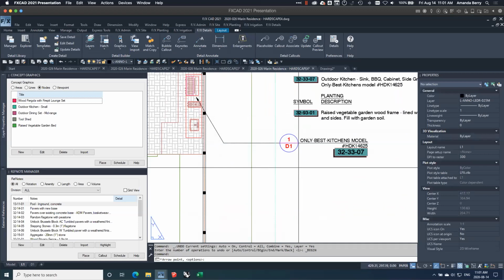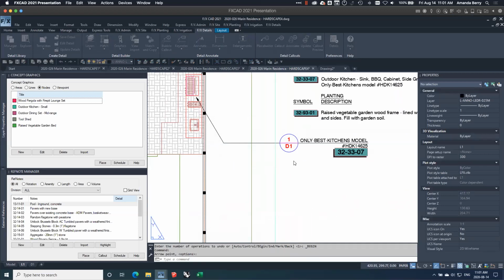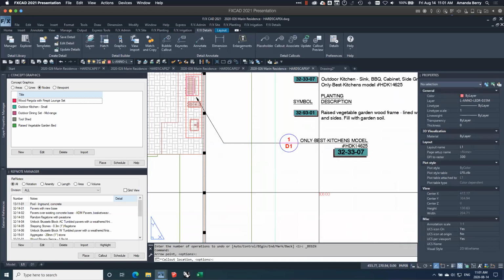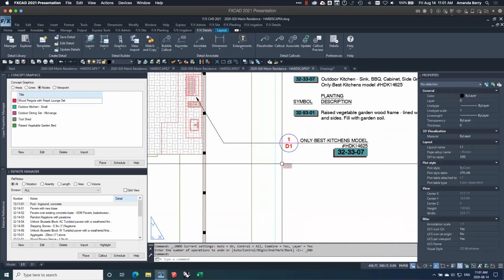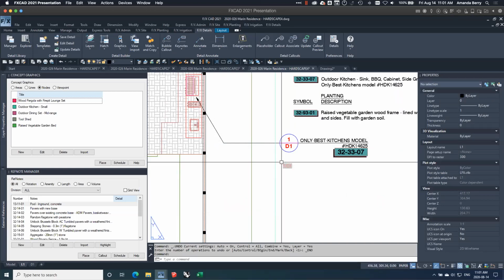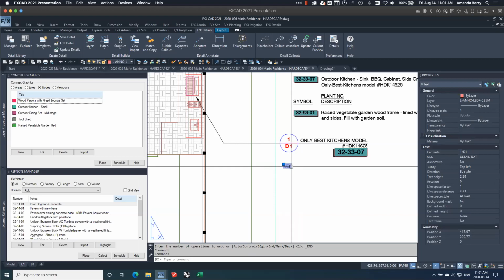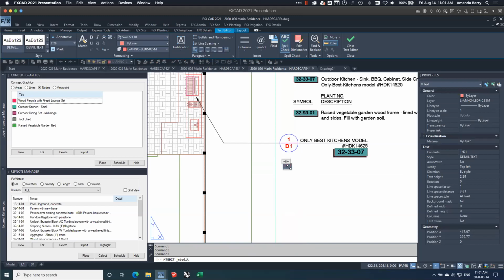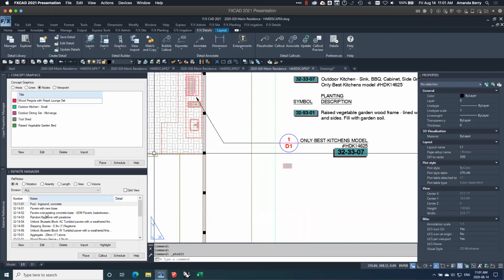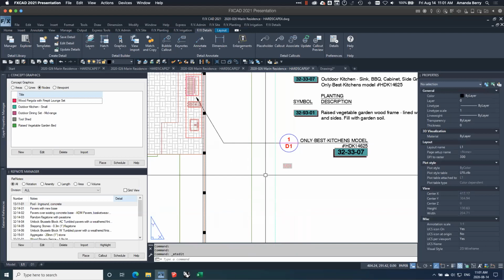Yep, and I'll probably sneak in here, if I right click at this point of placing the detail and I choose naked callout style. Just wanting to point this out that this might help you out, Kevin. And we do have, yeah, check this out. We've just documented it, but these are actually now fields that you can copy and paste into other MText. So that would help you out just a little bit. But in terms of actually associating it to the ref note, everything that Jer said applies.